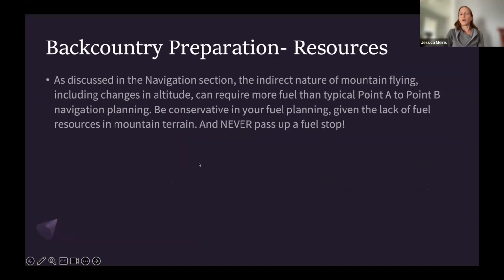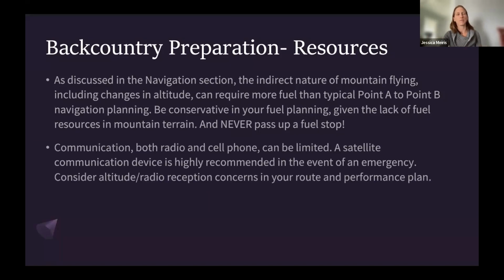Lastly, we'll move into some backcountry preparation. So as discussed before, a lot of resources might not be available to you in the mountains. You're going to have more challenging communication. You won't have as many opportunities for fuel stops if something does go wrong or your fuel calculations don't quite turn out the way you expected. And I would recommend to never, ever pass up an opportunity to get fuel, even if it's 10 or 15 gallons. Well, that can certainly make a big impact in your ability to handle something like an unexpected headwind or a diversion and reduce your anxiety of having to constantly do that math. So never pass up a fuel stop.